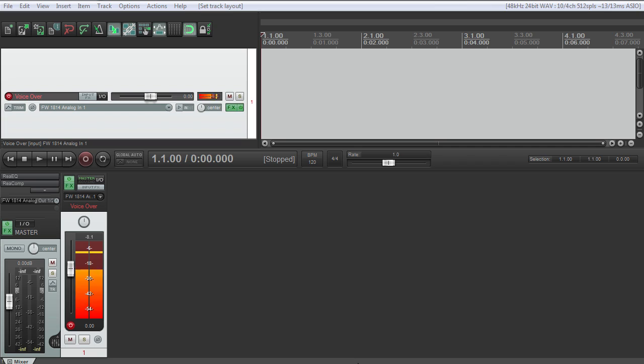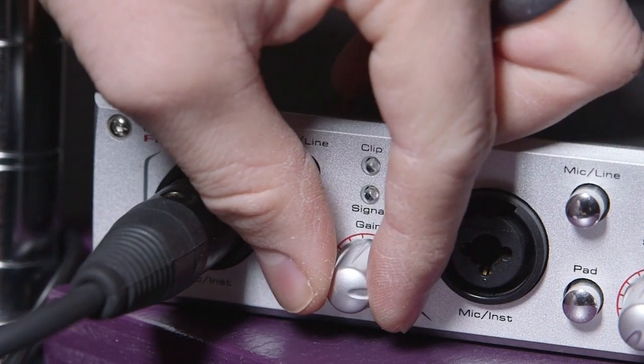You don't want to clip the recording level, so if you are seeing peaks that are getting close to -6 or higher, you're going to want to back down the preamp a little bit. A tiny bit of clipping may not be noticeable and can be recovered to a degree in post-production. You don't really need to record a super hot signal anyway, because the noise performance on modern equipment is very good. The best idea is to play it safe and keep those peaks around -10 decibels.